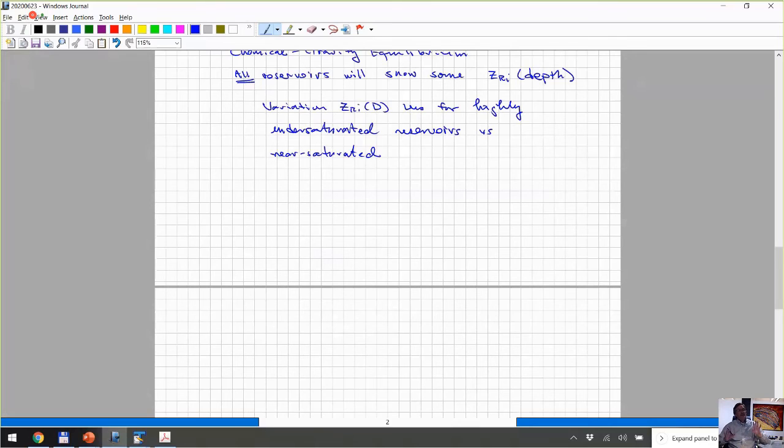So if everything else is the same and you just change the initial pressure, you start with the composition, you're going to calculate up and down, and you just give it an initial pressure. If you give a very high initial pressure, then that gradient calculation will give you much less variation than if you put the initial pressure at that composition equal to the saturation pressure.